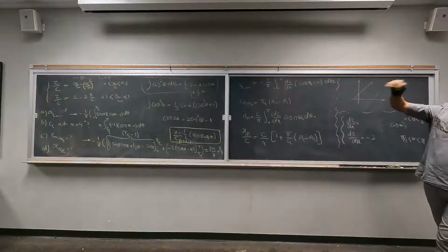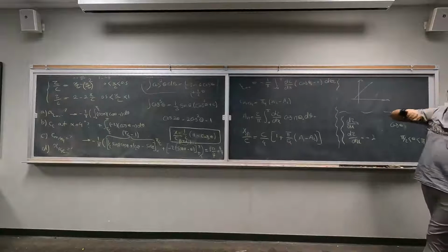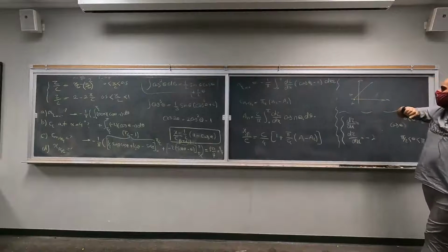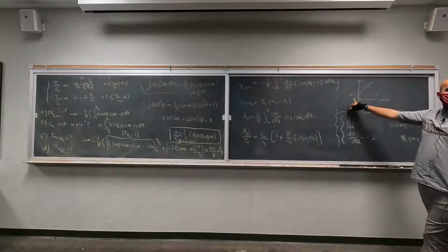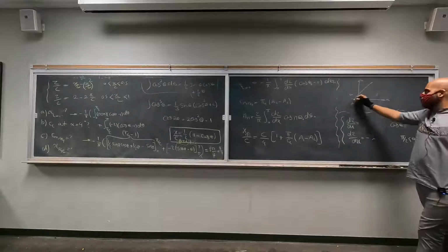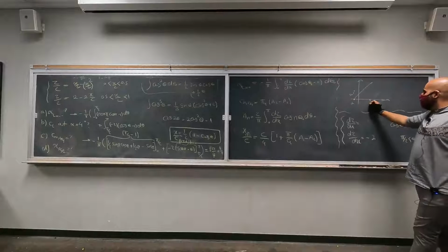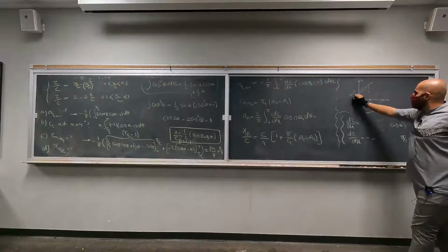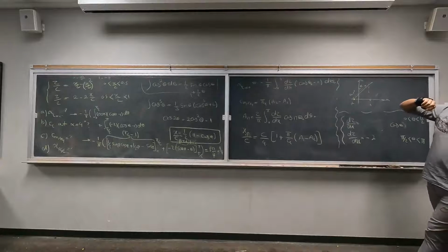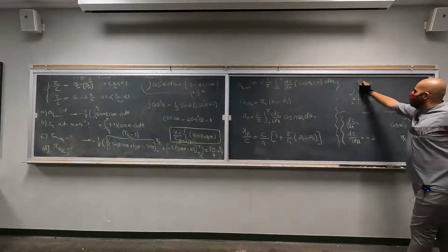We don't need to calculate that equation because we are assuming that CL versus alpha is changing linearly, right? And we have CL here, we have alpha here. What's CL at this point? 0, right? That's the idea. Zero lift angle of attack. So CL is 0, and we have just calculated alpha. We have alpha 4, and we know this slope is 2 pi, right? That's what we already know. So based on this information, how can we find this value CL?